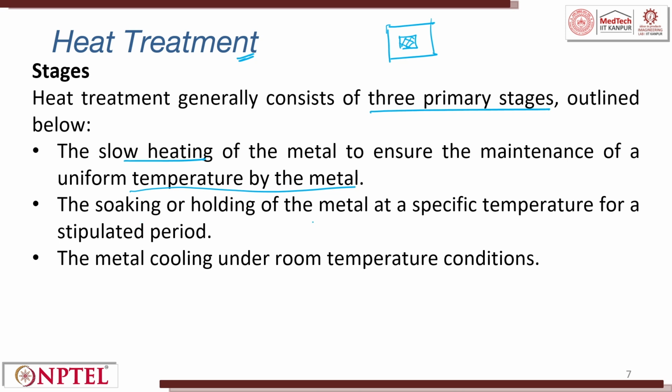The soaking or holding of metal at a specific temperature for a stipulated period is soaking or holding. So, what I am trying to say is, I will slowly heat it. This is temperature, this is time. I slowly heat, then I maintain at a certain temperature, then I slowly cool.